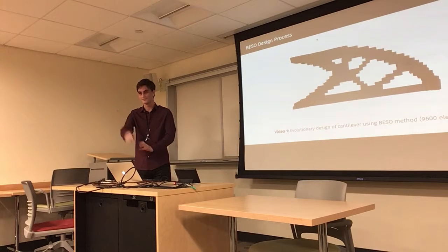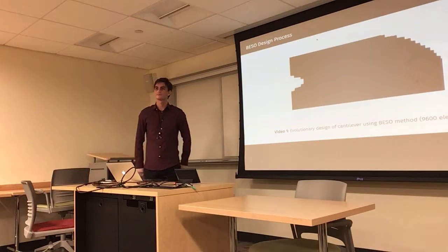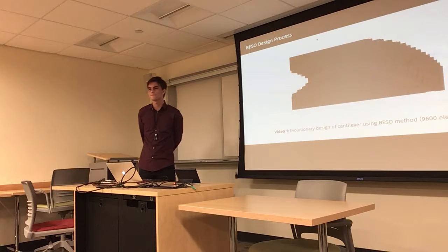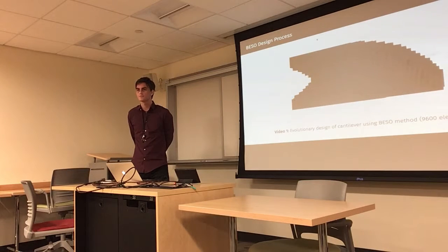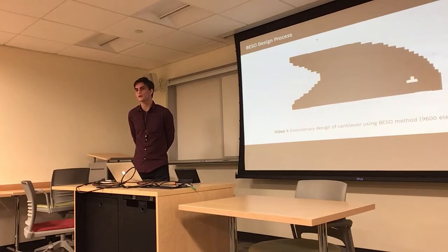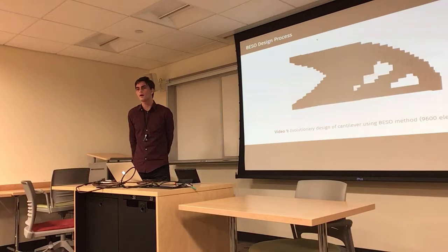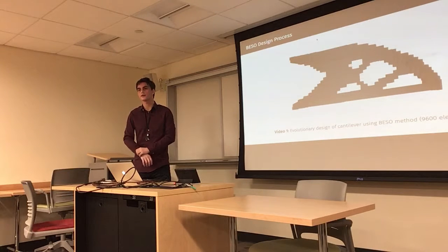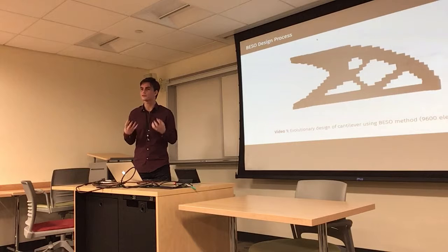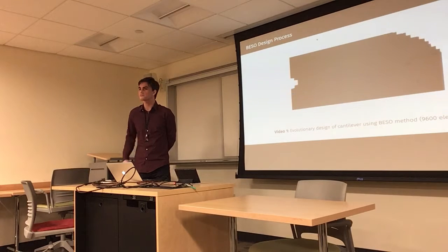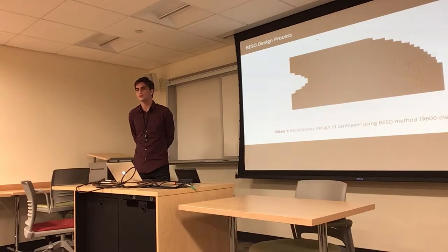Yeah. So is this method more about like maximizing the weight, or like maximizing the amount of weight you can cut from a part? Yeah. So typically, you can like say you want to take out 35% or something, and you can look at the finite element analysis to see if that part is good enough for your needs, because sometimes your part is just too massive and you don't need that much mass.